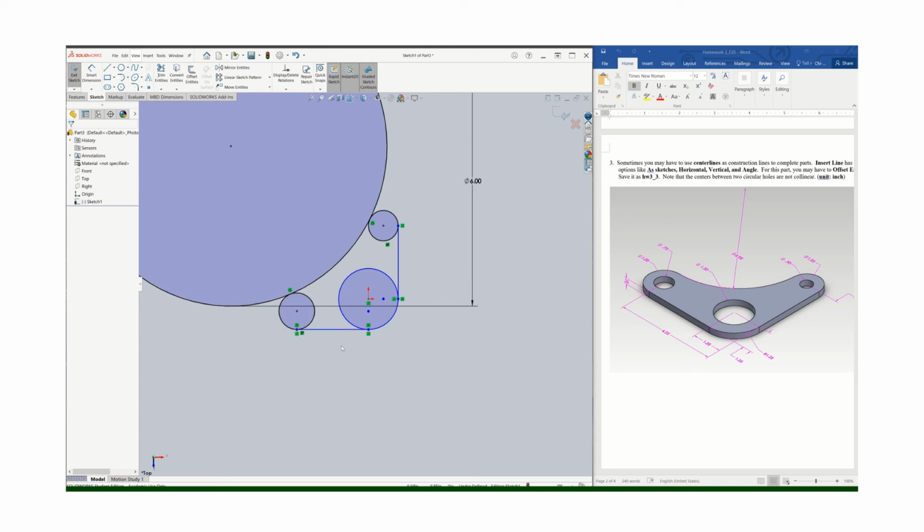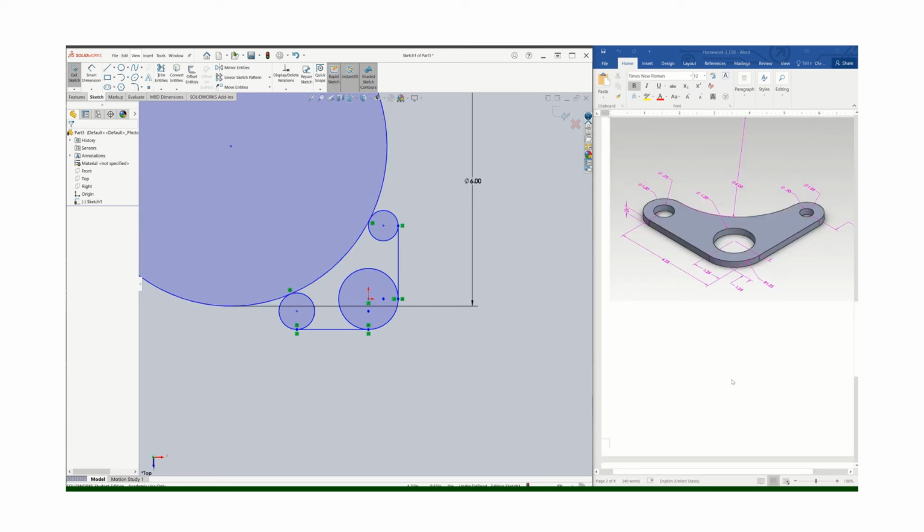And if you want to remove those extra constraints, then choose that symbol, right click and delete. Then that's gone. Again, choose that anchor, and while it's highlighted, right click and delete, and that's the basic geometry you can get, and you could finish this part.